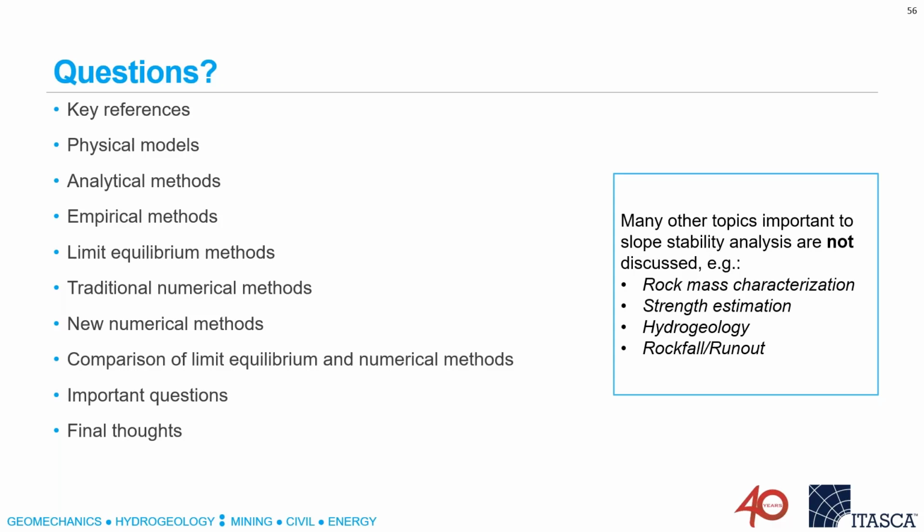So what does that tell us? It tells us that, first of all, these failures are probably largely frictional, and this is in the area where normal stresses are most important because they change. Once you get to depths beyond 50, 75, 100 meters, there's just too much confinement for rock masses to fail, so they don't fail at those kinds of depths.